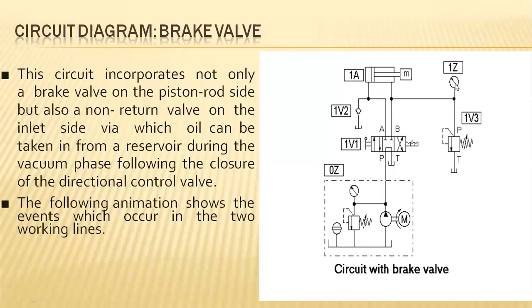The pressure relief valve, maintained at a set pressure, will allow the fluid to flow through port number 2 in the cylinder, and this creates the backward movement. At the time of this backward movement, the fluid already entered here will have to move in this direction.